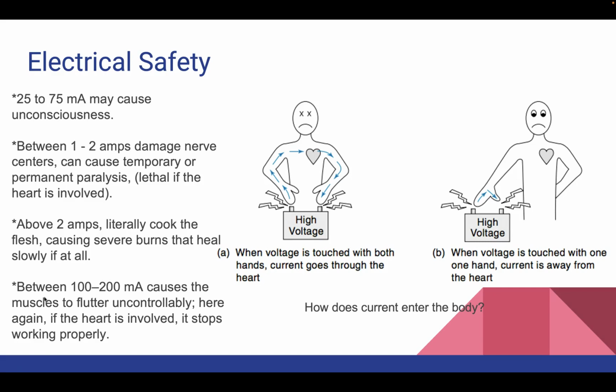To mitigate the risk of electrical hazards, it's crucial to implement safety measures. In high voltage areas, using rubber mats on the floor, wearing gloves, and using non-conductive fiberglass ladders can help reduce the possibility of someone getting shocked. Also, before working on electrical equipment, always ensure that the power is turned off.